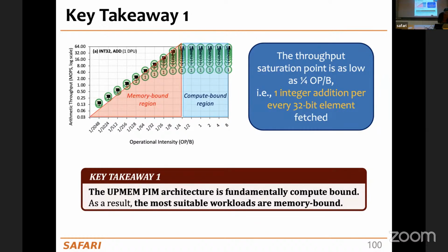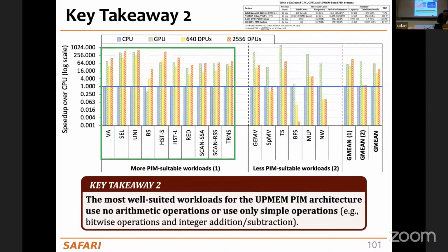So that's where we have the bottleneck in this system, in the computation itself, the execution of instructions, which, by the way, has one advantage. If I know that the problem with my system is the number of instructions I execute, what I should try to do is reducing the number of instructions that I execute. If you try that in a CPU or in a GPU, not always executing fewer instructions translates into performance improvement, especially if the workload is bottlenecked by the memory access, right? But here, we got rid of that problem. Now the problem is a different one, that we want to write programs that are more efficient and execute a lower number of instructions.